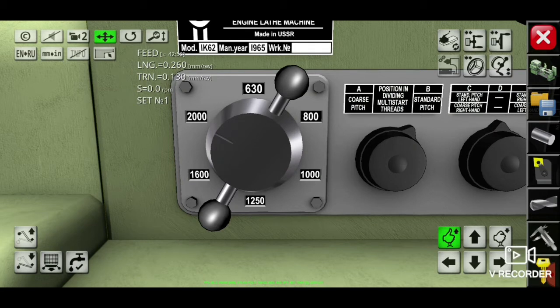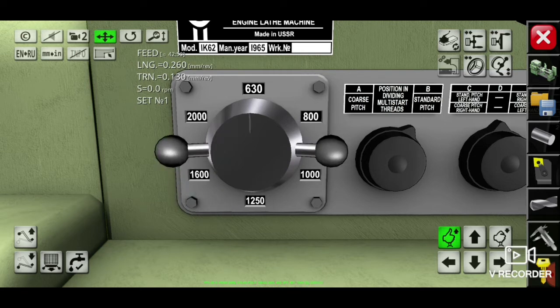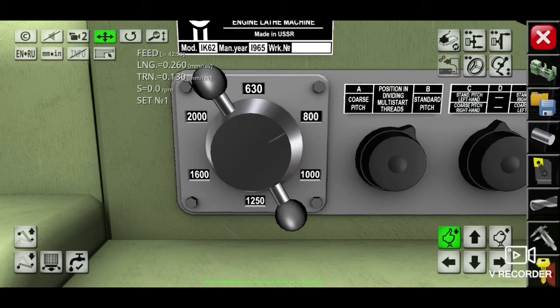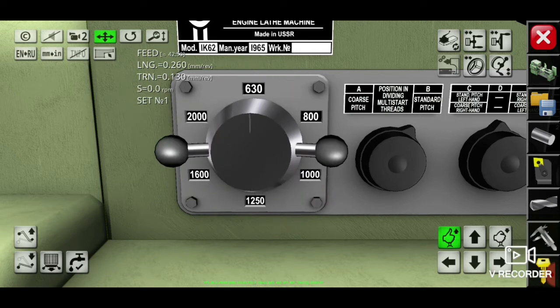In here we can see that there is no 700 RPM. There are only two options actually, 630 and 800 RPM. In this case, we will choose the lower one, 630 RPM, because if we choose the high one, we're afraid that in the real condition, our cutting tools will face wear. So to save this, we will use the lower one, 630 RPM.